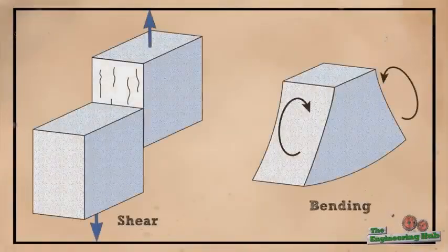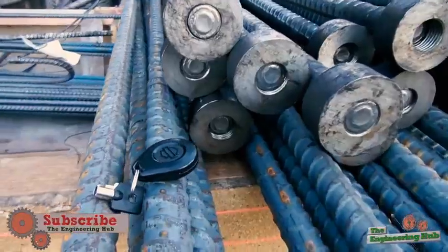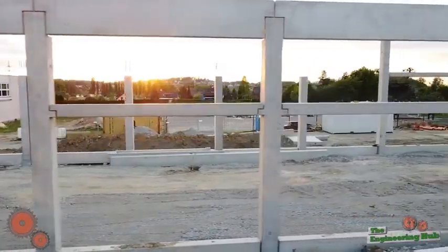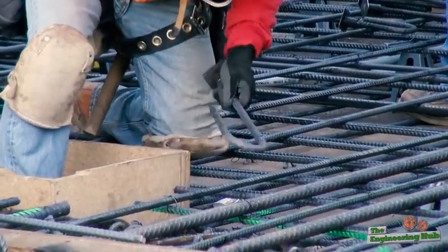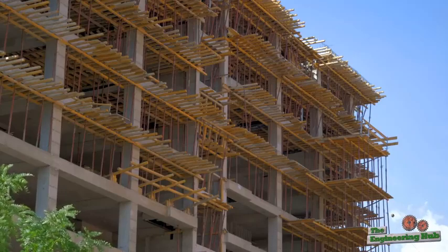The bending and shear loads are the most important design considerations for a simple beam loaded concentrically. These forces guide the design of the beam in terms of size, amount of steel, and length. But how does a concrete beam resist these forces, and why is the steel reinforcement even necessary? The answer lies in the nature of concrete as a material.